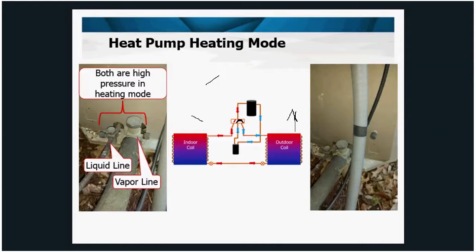So when you're on a heat pump system and you may be in the air conditioning mode, you'll want to connect to the liquid line service port like you normally would, but then you'd also want to connect to the low side port, which is usually through the cabinet like this. Now, this is usually like this. Some of these ports are directly on the line between the accumulator and the compressor. They don't extend outside the cabinet. You have to kind of look. Different makes have different setups.